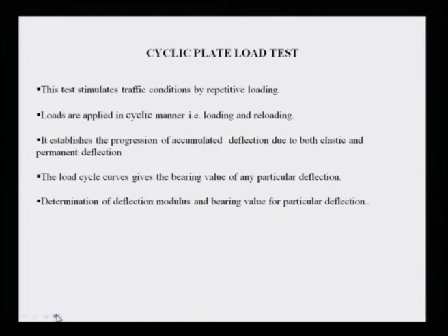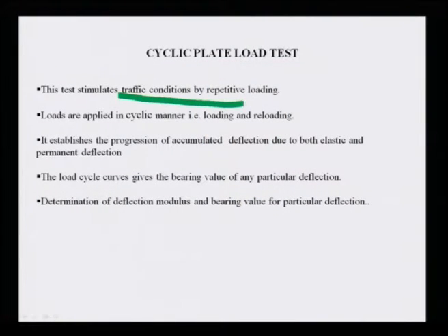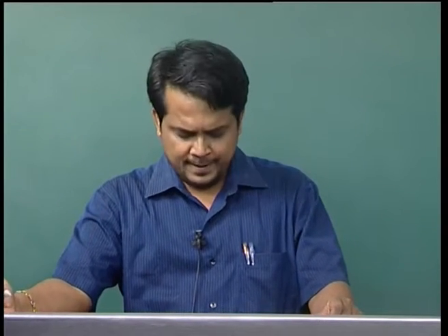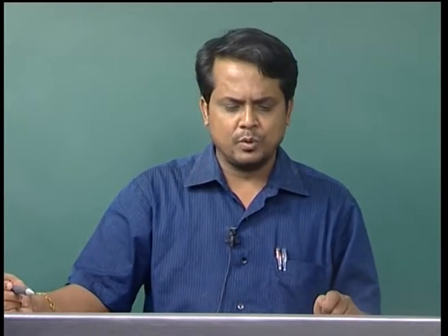Then the next question is, with this plate load test, will it be possible to conduct a cyclic plate load test? Yes. Generally a cyclic plate load test is required to simulate traffic conditions by repeated loading. Loads are applied in a cyclic manner, loading and reloading, that means after the first set of load you apply in the plate load test, in the next step instead of applying the second increment of load you can reload it. Then after reloading you apply your second increment of load.